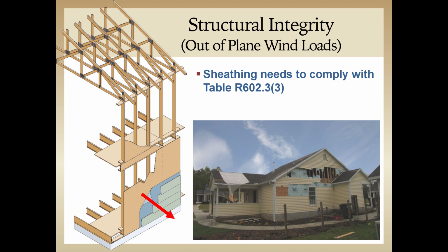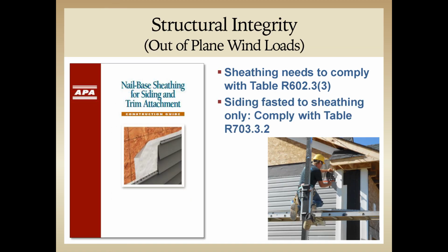If you think back to our structural integrity discussion, you'll remember that we talked about the effects of 24-inch stud spacing on the sheathing when the walls experience suction loads. What we didn't discuss was the effect of this spacing on the siding. The ability of wood structural panels to serve as a nail base for siding with 24-inch on-center framing is something that has been studied. Some popular sidings are limited to a maximum nail spacing of 16 inches, and we wanted to make it as easy as possible for builders to make the switch to 2x6 advanced framing.